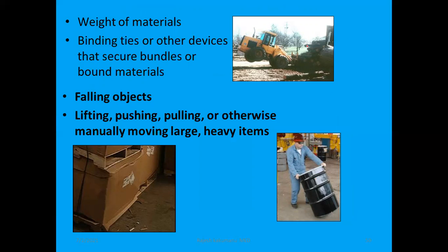See here, this person is removing this log, lifting the tree stumps. Whenever this process is being done, whenever the weight is overbalanced and not equal to the counterbalance, automatically when we lift, the truck rises up. Why? Because you are not maintaining the proper balance. The counterbalance also should be equal. Otherwise, what happens? This type of mistakes you have to face. See this one, improper setting, improper binding. There is no proper binding of the objects, right?